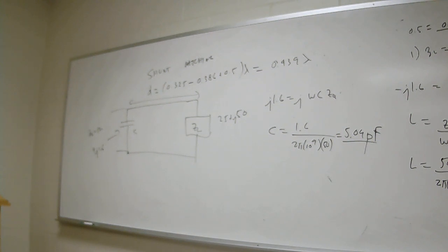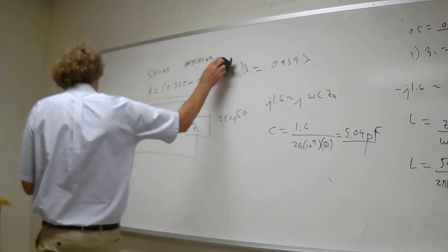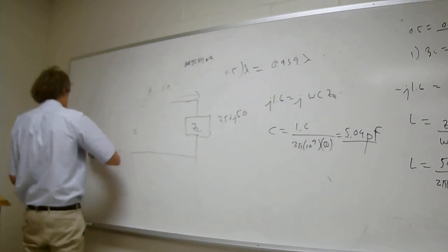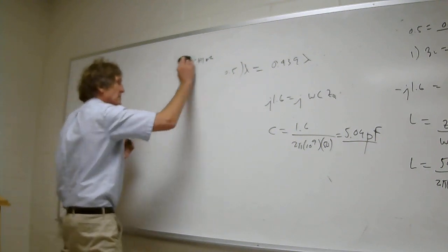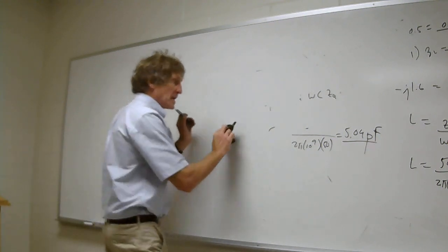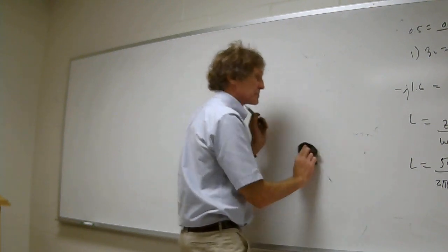And I showed you the two ways of matching in series using impedances, right? We're always using either inductors or capacitors because they draw no power for matching. Y'all with me? Now what we're going to do is actually use a transmission line to replace the inductors and capacitors. First we'll start with series matching, even though I could do it in parallel right now too. I'm going to show you this. This is not the most common way it's done, by the way, but it is done often enough that Whitmer's book talks about it, and frankly, it's worth knowing how to do this.